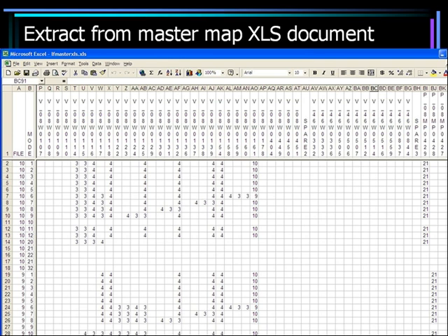There's a small section of the map file. Across the top we've got fields. The field names, as we said, do matter. The last 8 characters in the field name there, for example, looking at the first one there with numbers in it, about the 5th or 6th one across, it's V_08W0114. Well, the 08W0114 is a name that matches a configured entity, being the piece of equipment that we're concerned with.